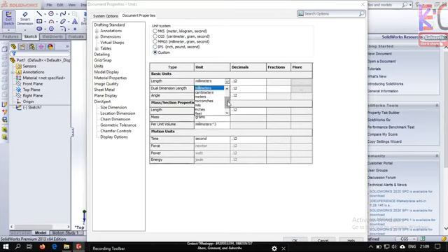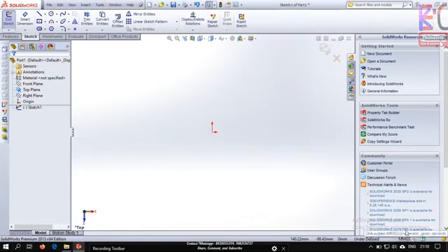So here you can change from, yes, you can see angstrom, nanometer, micron, from the minimum to the maximum, feet, inches, everything. So you have all the things you need, whatever you can think of. So I'll go for MMGS, then I'll click on OK. As you can see, my unit gets changed.